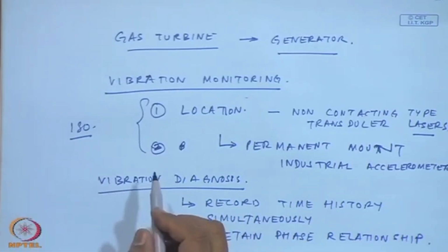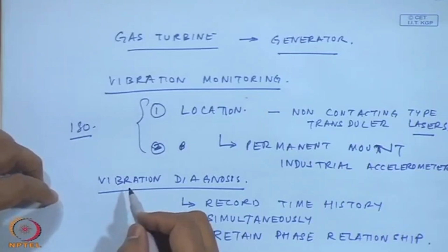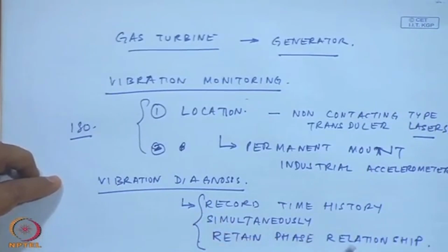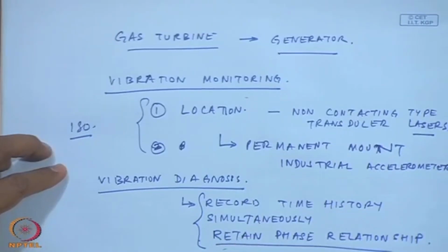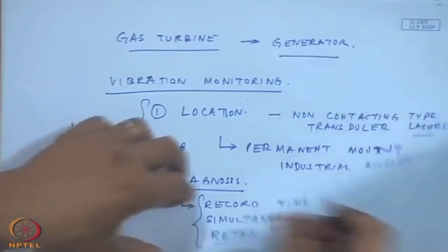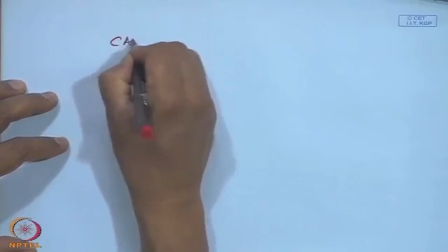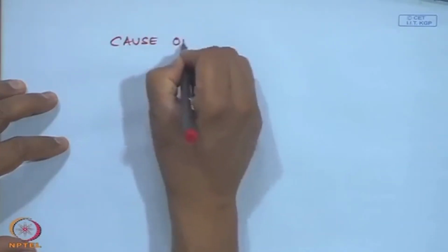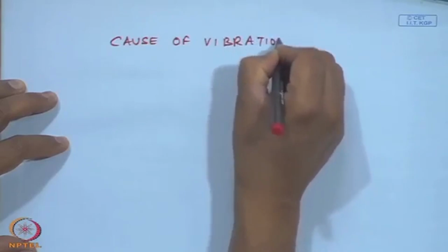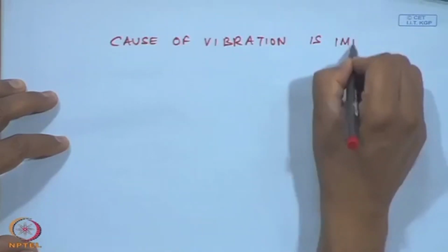So, as a condition monitoring and machinery fault diagnostics engineer, we would be more interested in recording the time history simultaneously, so that we retain the phase relationship, so that we can know the cause of vibration, which is important.